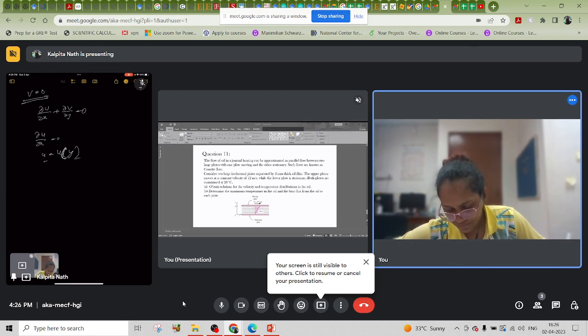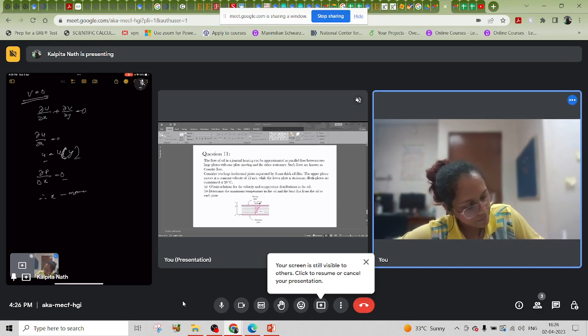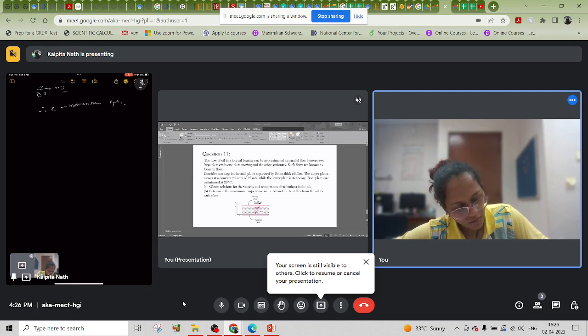Now, u is a function of y, v is 0, and the pressure gradient del p by del x is equal to 0. Flow is maintained by the motion of the upper plate rather than the pressure gradient. So the x momentum equation, as we wrote the previous day, will be rho times u del u by del x plus v del u by del y is equal to mu del square u by del y square minus del p by del x.